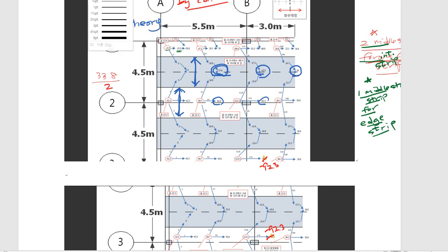Alright. Based on beam theory. What's the beam theory? Moment is As Fy (d minus a over 2). This is beam theory, right? So we assume depths of the slabs, which is the depth of the beam, and you can calculate the depth of the compressive concrete block.